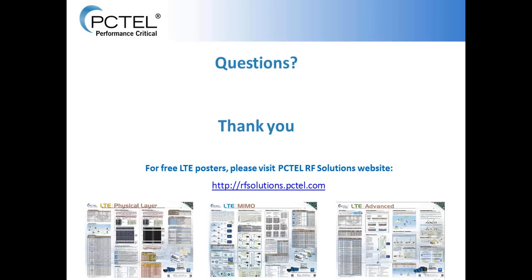And the other common source is PIM. The reason why PIM is so common is probably 2 reasons. It's caused, let's say, by the rusty bolt effect, dirty connectors, and this type of thing. A lot of the towers these days, at least the newer ones, are moving more towards fiber optics, but pretty much most of what's been deployed are cables that are actually running up the tower. And these cables have connectors on them, and these connectors are rusting. They're becoming loose because with weather and heat and cold, they start working themselves loose, and they cause PIM.